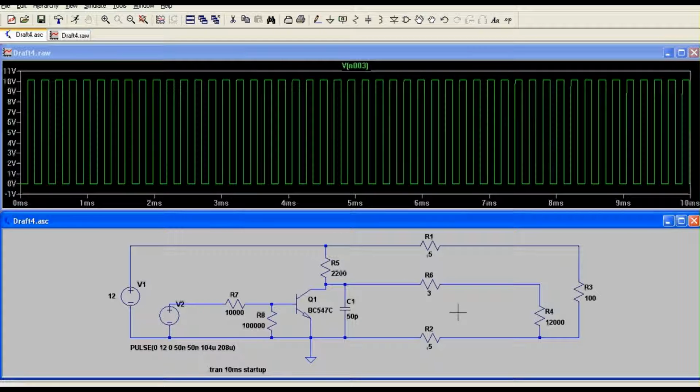And here I'm trying to simulate some cable lengths. I've got positive feed coming through this wire here, and then through R3, which I'm saying is representing kind of a system load, and coming back through the return on R2. So I'm saying, 50 to 100 meters of some certain type of cable, you might see that as 0.5 ohms worth of resistance on this runner wire here and this runner wire here.